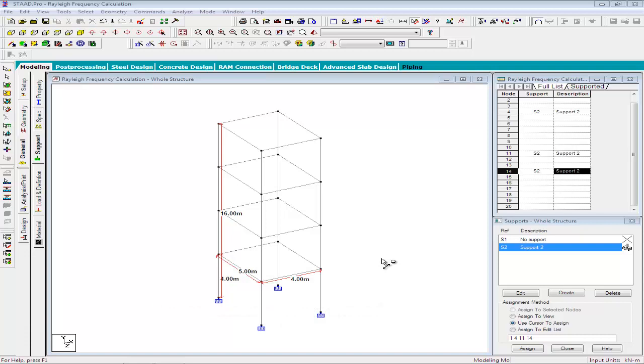The Rayleigh method in Staad is a single-step approximate method from which we will obtain a single frequency value for the loading that we have provided. Staad Pro will calculate the frequency value for each and every loading that we have provided in the load case definition. The program uses the displaced shape of the model to obtain the frequency. So it is extremely important that the displaced shape that our loading can cause should resemble the vibration modes for which we are trying to calculate the frequency.